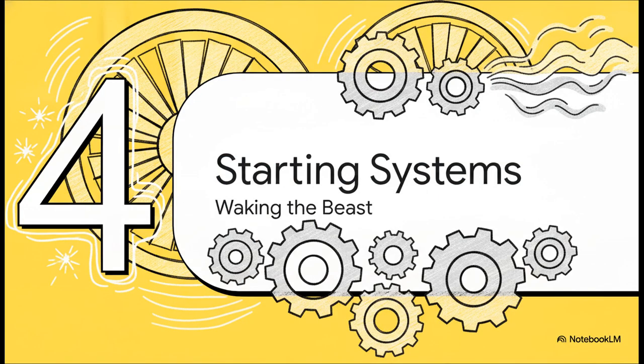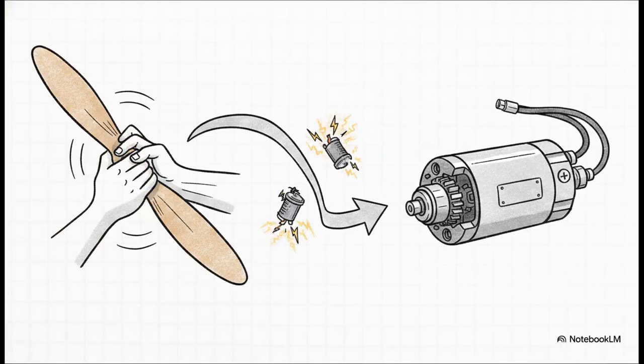Finally, we close the loop with Module 4, Engine Starting Systems. Because before any spark can ignite any fuel, we have to physically get these gigantic engines rotating. We'll take a quick walk through the historical evolution of reciprocating starters to understand how we got here. We actually started in the terrifying early days of hand propping, literally pulling a massive propeller by hand and just praying you don't lose an arm to a cold, stiff engine. Yeah, no thanks. Thankfully, we evolved to inertia starters, and we developed auxiliary starting aids like booster coils and the shower of sparks induction vibrators to help out those weak magnetos at low speeds. But today, mostly you'll be working with modern direct cranking heavy-duty electric starters.